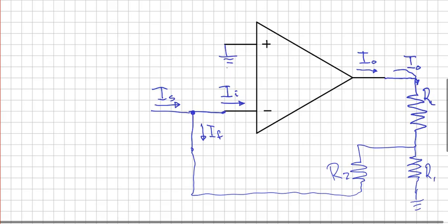So that works. When you're connecting a sampling network for current, they call this current sampling, you need to connect it on just like you would an ammeter. Your ammeter has to have the same current flowing through it as the current that you're trying to measure.